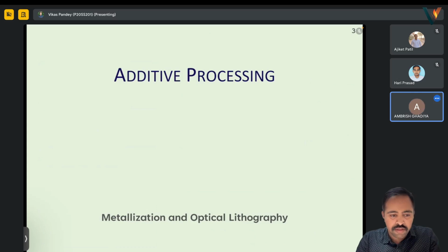There were four options. Longer mean free path ensures more directional travel to the substrate. Shorter mean free path increases collision and scatter. Mean free path has no effect on directionality of atom travel. And longer mean free path reduces the deposition rate. So what according to you should be the correct answer?